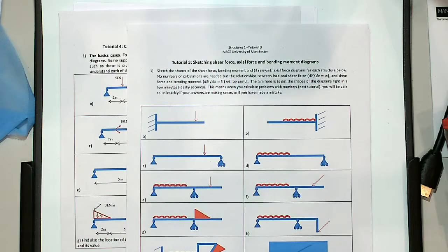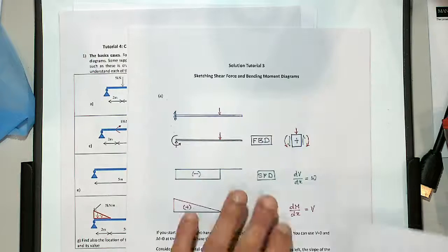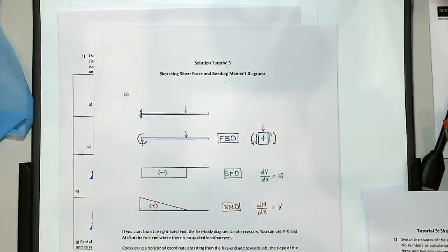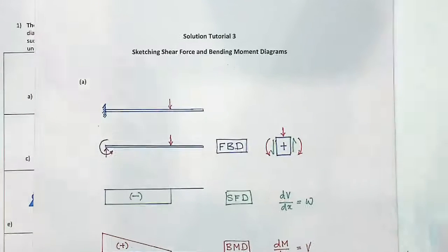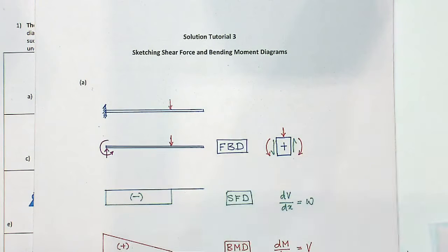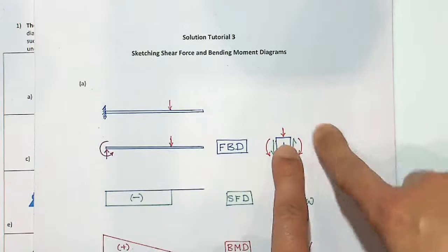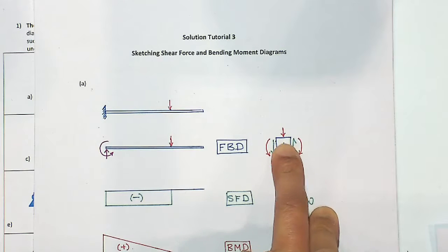So that's about the sign conventions. In terms of the sign conventions, this is the sign convention we choose: load downward positive, and shear force with the left side going down relative to the right side going up is positive shear force, and a hogging bending moment is positive. The bending moment is such that the beam element will bend upwards, so it is anti-clockwise on the left hand side and clockwise on the right hand side of the section.